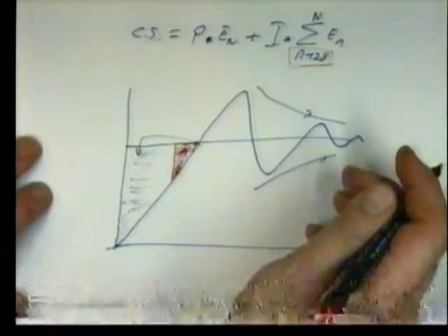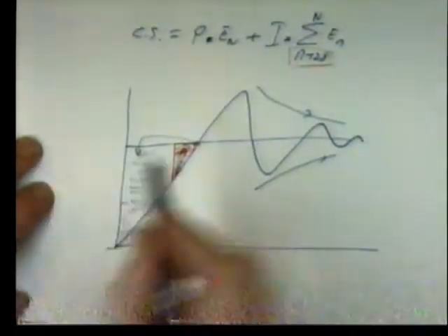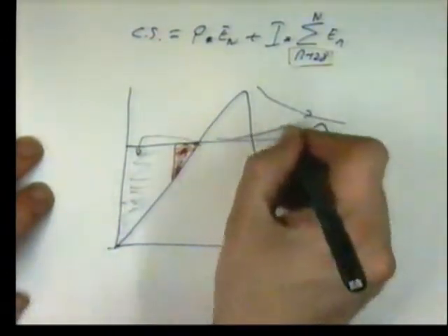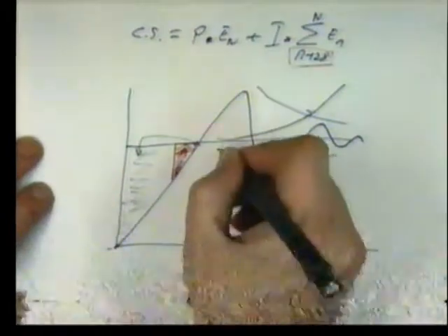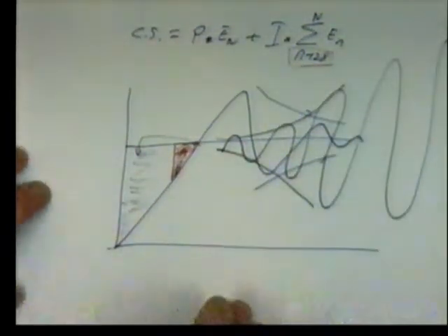If we're still having problems with the integrator going out of control, the effect of that is that instead of this exponential decay, it flips sign and it goes positive. And what happens is you start getting that effect. Our whole system will fall over. There are some other computational techniques you can use. One of them is the integral clamp, and the other is the integral reset. Let's run through what both of them do.